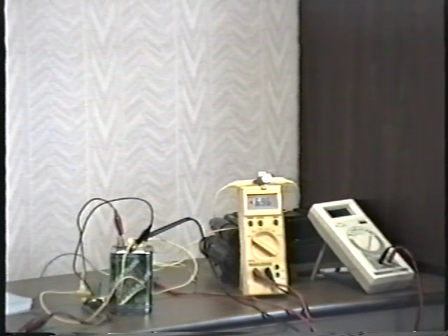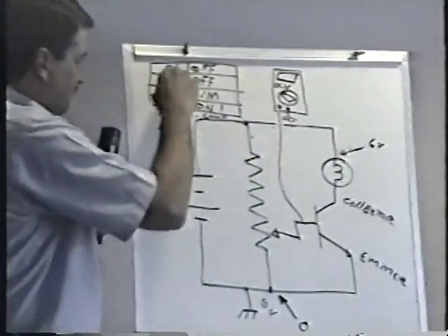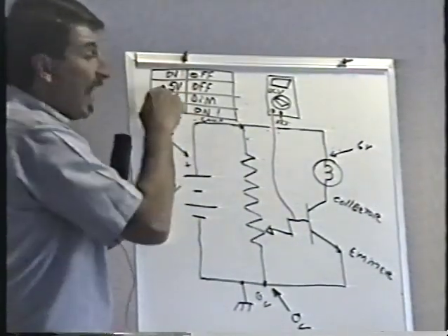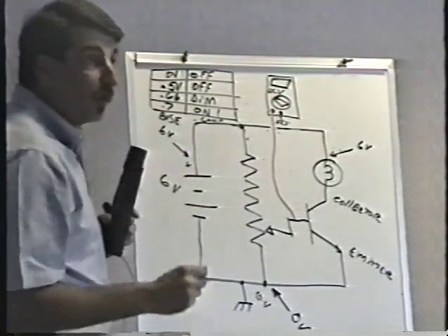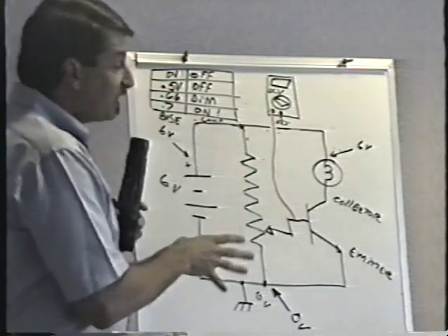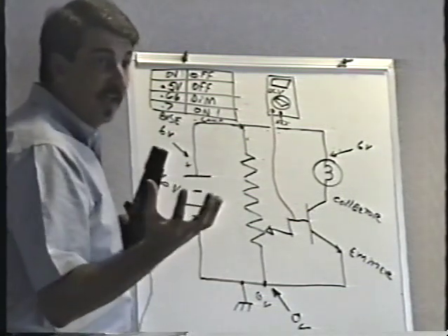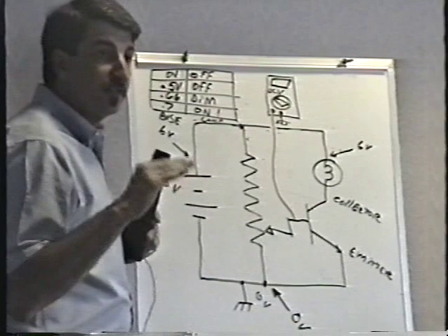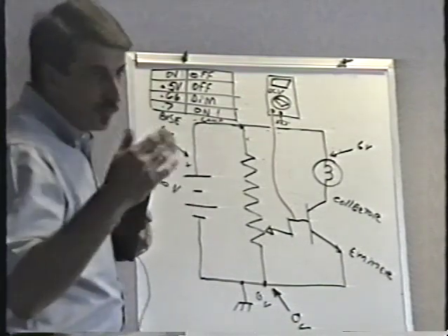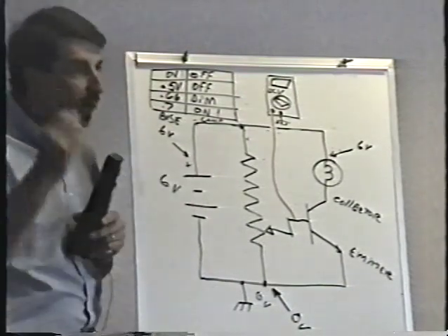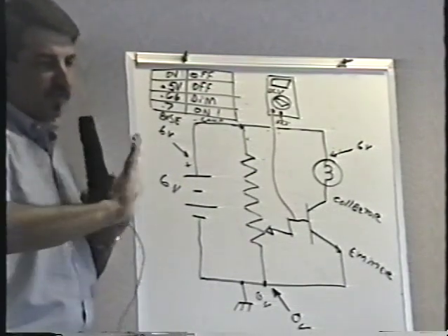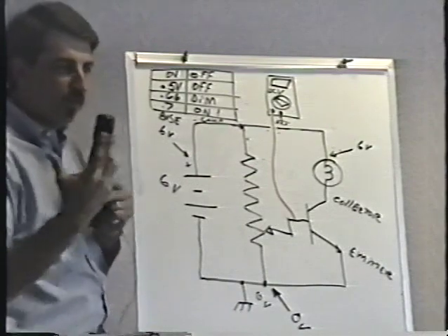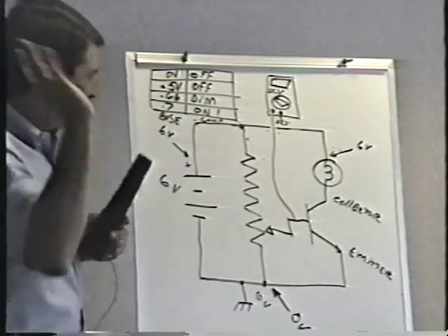So as the voltage increases, even at half a volt, we've got nothing on that lamp. It takes that 0.7 or so to get it turned on. Now, remember, 0.7 is an average. The larger the device is, the less voltage it takes to turn on. I know that really seems backwards, and when I first discovered that, I thought, what's going on here? Why is that? But a larger device has more surface area on the p-n junction, and so there's more electrons cruising around, and it doesn't matter.